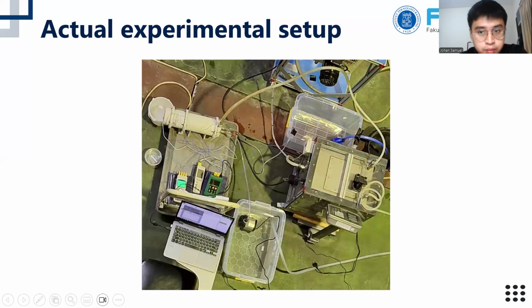And this is the actual setup. And there are some modifications to support the experiment. One of them is that there are 2 additional thermocouples attached on both ends of the heat exchanger. This is done to monitor the steadiness of the system, since the condenser wall temperature increases when steam enters the system. Eventually, the wall temperature remains constant at about 80 degrees Celsius.